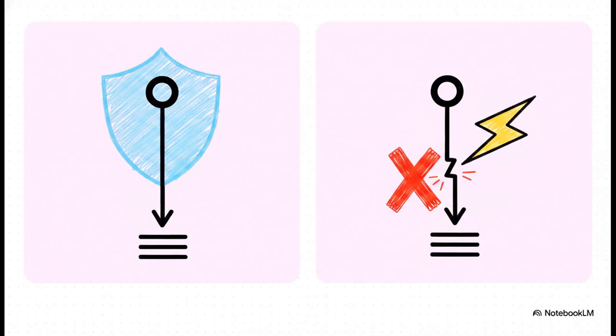Section: Neutral Grounding and Protection, moving from math to the real world. But per-phase analysis alone won't show you everything. It assumes a perfectly balanced system. When a system develops a fault to ground, physical realities take over. Grounding the neutral point isn't just a basic connection choice. It is an absolutely critical protection decision to manage fault currents.